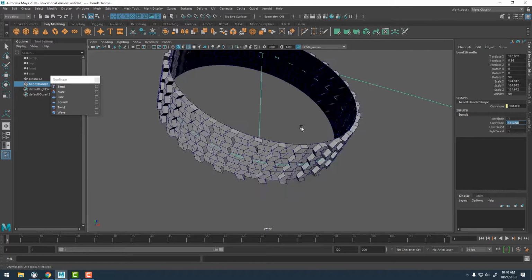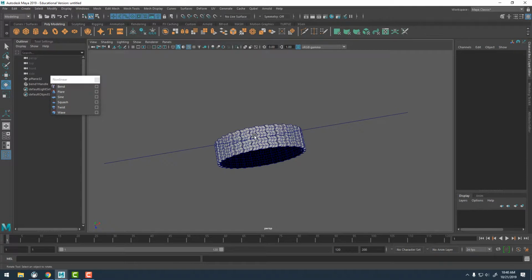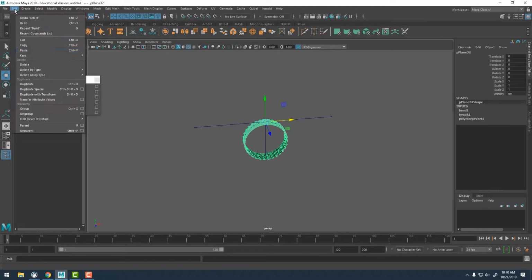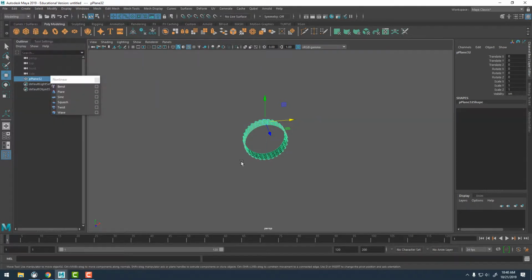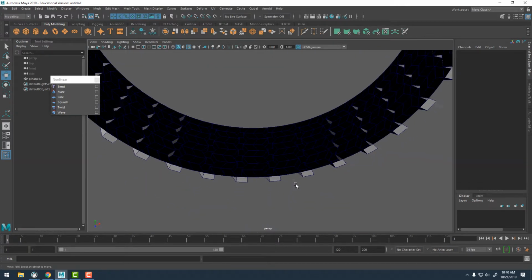And that's pretty close. All right. So if we want this to maintain its shape, again, it is relying on the deformer itself. If we pull this out, you can see the tread is going to go around the deformer. Let's undo that. Let's grab the geometry and go to Edit, Delete by Type, History. It'll delete the deformer. Now again, where we have that seam down here, those vertices aren't attached.